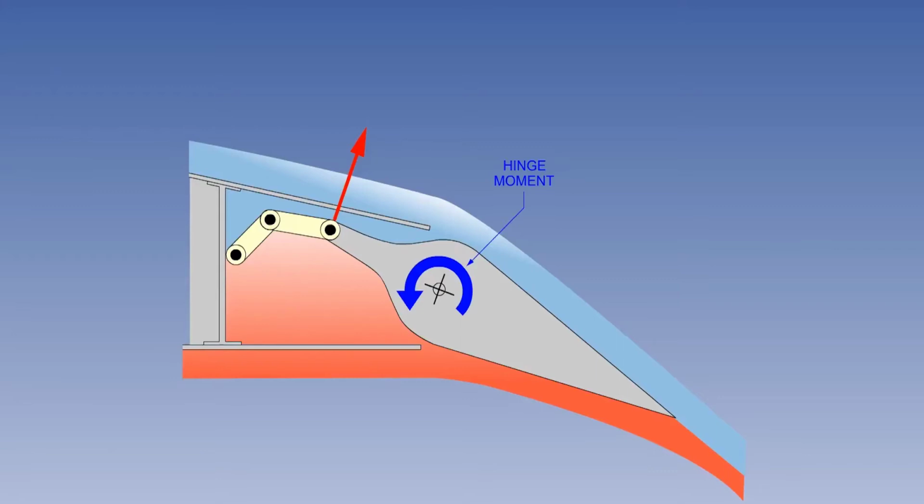The internal balance is very effective and is still used on some modern jet transport aircraft and business jets, even those with powered flying controls, as they relieve the stresses on the structure where the hydraulic actuators are attached.